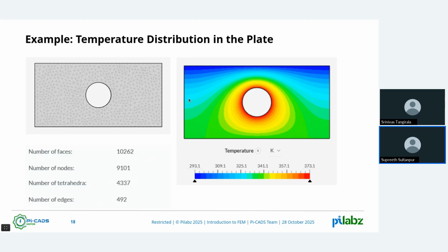We have only added fixed temperature boundary conditions. You can try adding, for example, natural convection, or forced convection, which will change the nature of the solution. Doing this analytically, for each of these boundary conditions you would have to find analytical solutions which have a completely different form each time. But in FEM that doesn't happen. It's just a change in a number or the addition of a condition, and the whole process remains the same. You don't change anything else, just the boundary condition.